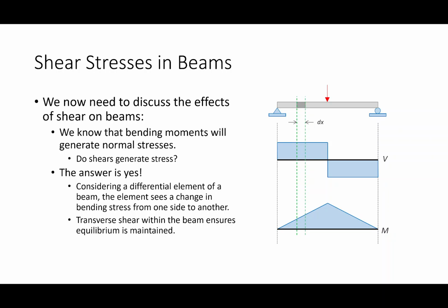That beam is subjected to a point load in the middle, right? So we know that if this is 10 kips, then these two reactions are 5 kips. So we go up 5, over, down 10, over, back up 5, right? Area of this goes up, area of that goes back down, okay? Now, the reason why I'm using this example is because I'm talking about shear, so I'm using about the simplest case that I can to illustrate an example of a constant shear, okay?